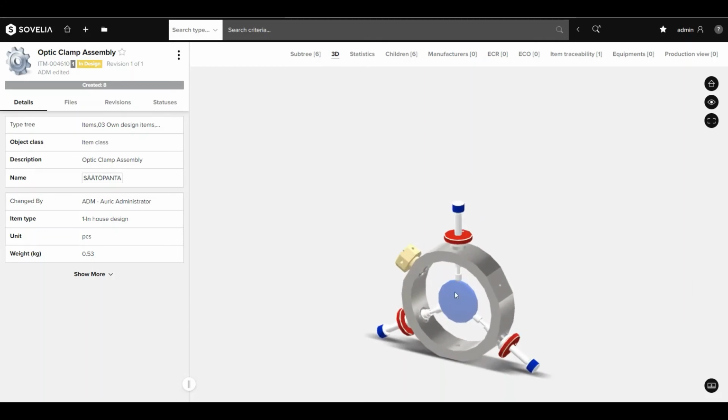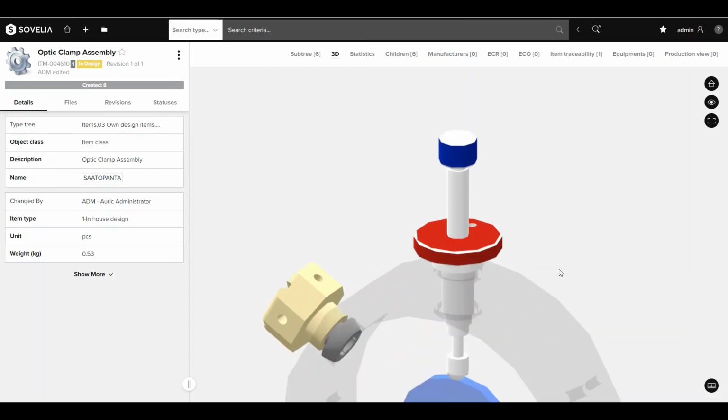A little bonus tip for you here is that if you select a particular part or item in the window, you can use your right mouse click and you can open the property card. You can pivot and make that the pivot point for your rotation. You can also isolate the part and it makes everything grayed out so you can just see that particular part. Once it's been isolated, you've got the option to right click and then show all again. If I select it again and right click, you can of course hide that view, showing everything else, for instance.